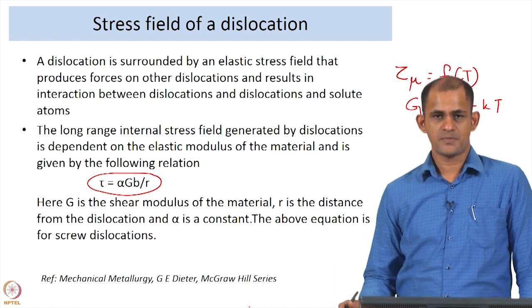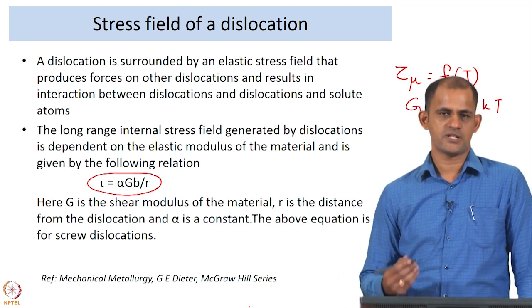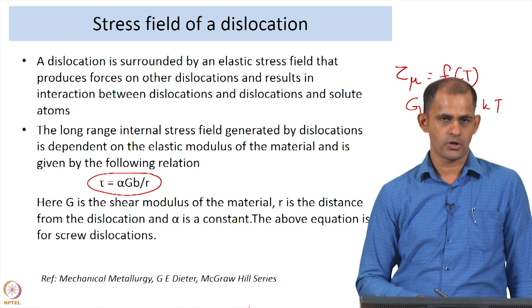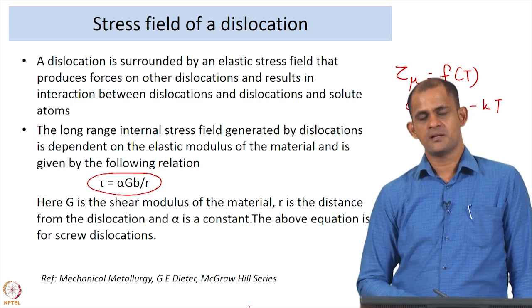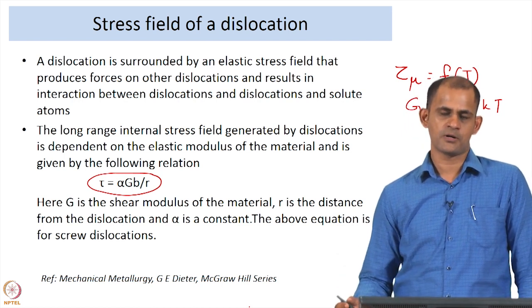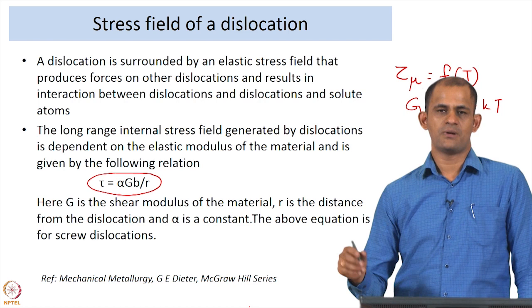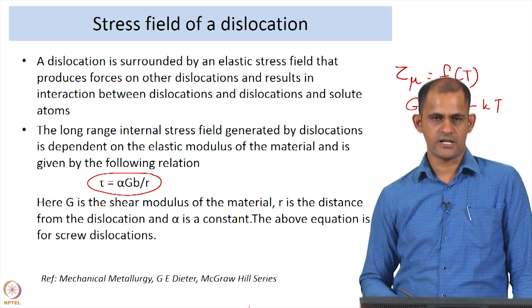What this also tells us is, as a function of temperature, the dislocation arrangements might change, and the change in dislocation arrangements and configurations is something I am going to talk about in the subsequent slides. And it also means that when you are evaluating this internal stress field or the thermal component of the internal stress field, you will have to account for the fact that the dislocation substructure or the dislocation configuration should not have changed.